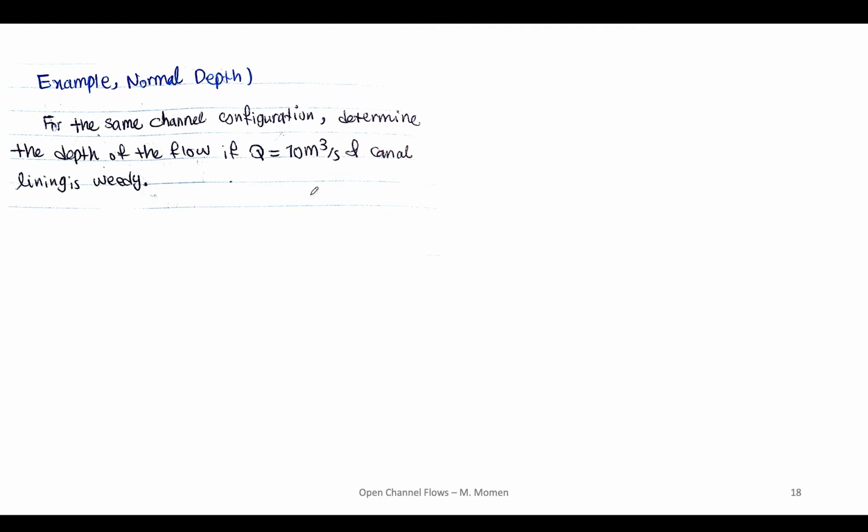Okay. In the second problem, I want to find the normal depth in this kind of open channel flow system, and it's a little bit more tricky because we will see that you have to solve a nonlinear equation, like we have to find the root of a nonlinear equation. And we can do it either with trial and error like we did before, or you can solve this numerically, or just give this to a software or a calculator and find the roots in the problem.